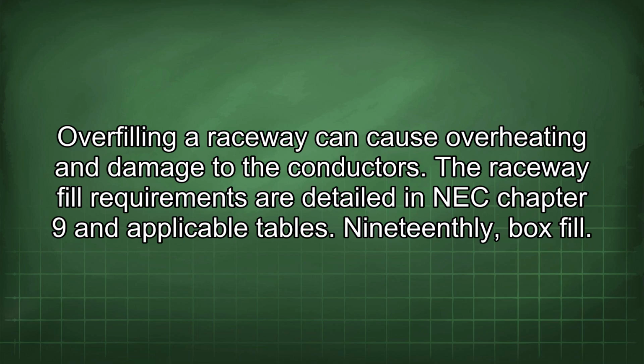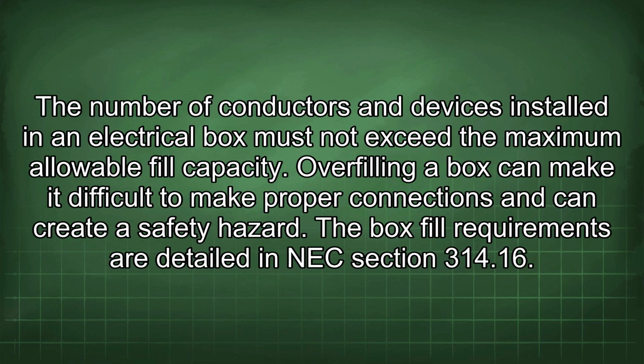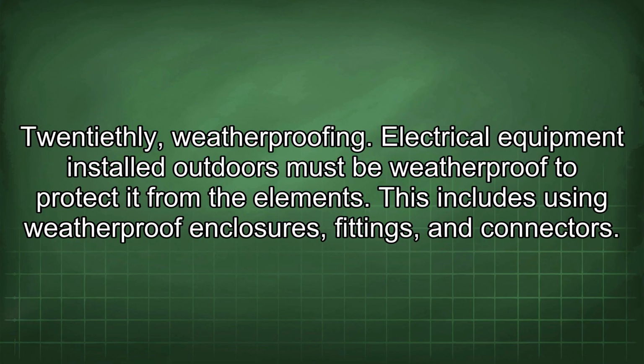19thly, box fill. The number of conductors and devices installed in an electrical box must not exceed the maximum allowable fill capacity. Overfilling a box can make it difficult to make proper connections and can create a safety hazard. The box fill requirements are detailed in NEC Section 314.16.